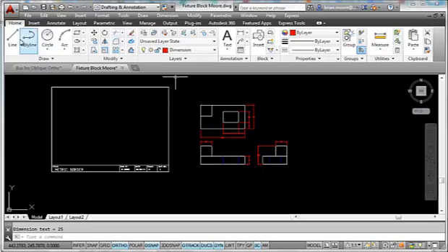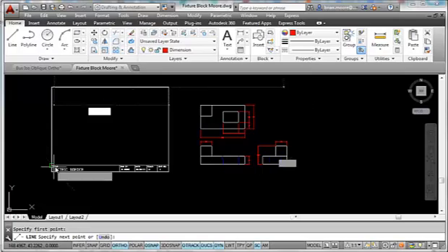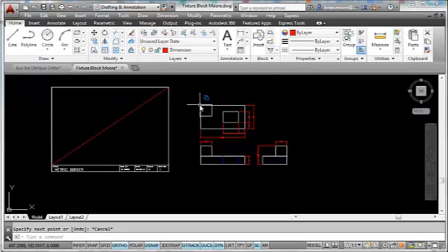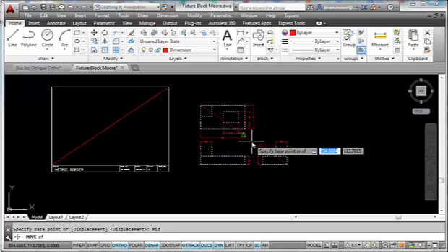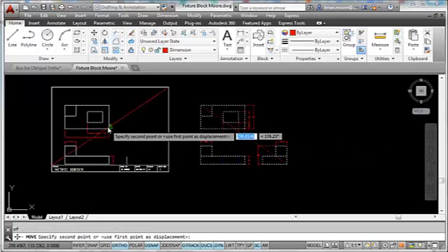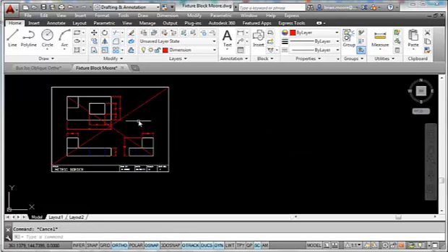So I'm going to use the same methods as I've used in the past. I'm going to center the smallest rectangle that will fit around the object, which would be this. Now the entire view is my object, so I'm going to draw a line. I've got 2 corner points already, so I don't need to draw any others. I can do M for move the whole thing from the midpoint. I'm going to make sure I get a midpoint of that line, so that gives me the midpoint of that line, and then this one will be easy to find. And now it's perfectly centered.